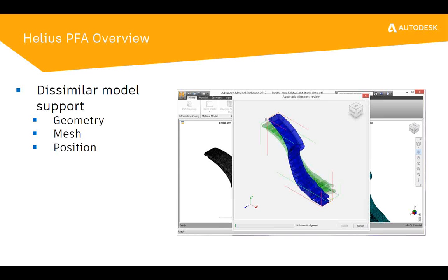It's just a temporary alignment. It's not changing nodal coordinate locations or anything like that. It's just a temporary alignment so that we can accurately transfer properties across. The original FEA input file is not modified, so we still have the same nodal coordinate systems.